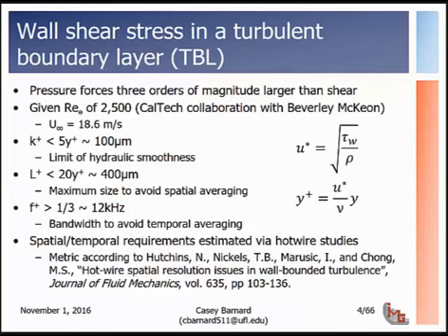Additionally, there are a number of different temporal and spatial scaling requirements to do full resolution of turbulent boundary layers. The 3 key metrics include the front side smoothness, known as hydraulic smoothness, basically how rough is your front edge so that you're non-disturbing to the flow, the characteristic length scale of your primary sensing element, and also the bandwidth, of course, of your sensing device. For a low-speed characteristic boundary layer flow of, say, Re theta 2500, those limits would be about 100 microns in smoothness, 400 microns for your floating element size, and 12 kilohertz of bandwidth. And that's for full resolution of all the turbulent scales.